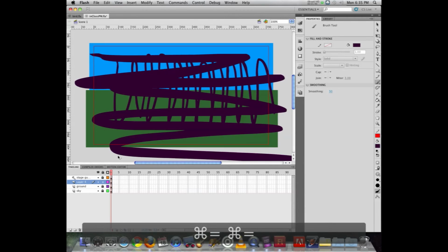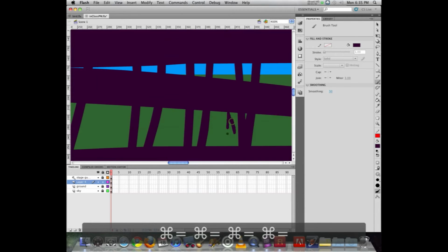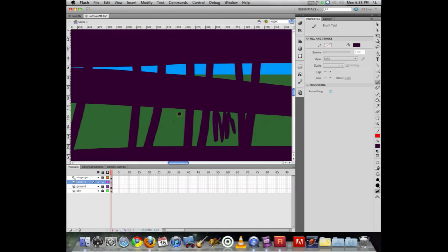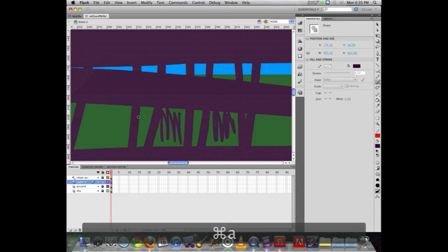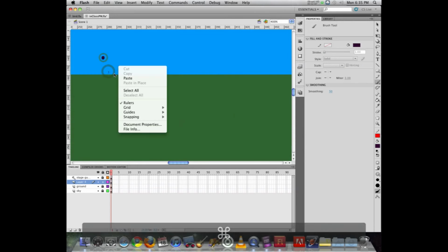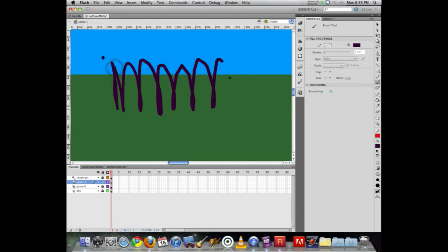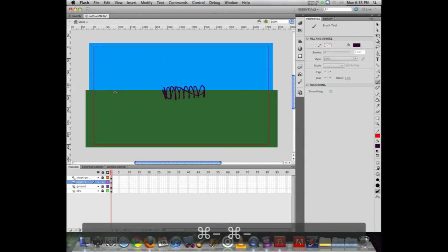Now if I zoom way in, it's still making that same mark. So if I were to put my finger up to my screen, it's the same size mark on my monitor. So unlike in, say, Photoshop, where you make your brush bigger and smaller, in Flash, your brush gets bigger or smaller based on your zoom level. So if I want to make something that is really detailed, I can zoom way in and then draw, because then when I return to 100%, we can see that that becomes a much smaller line.